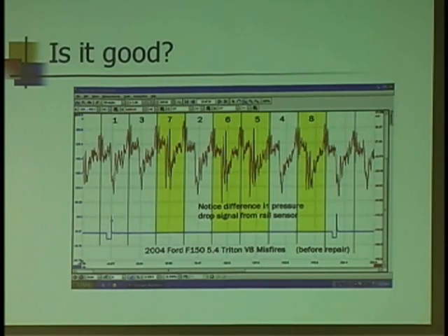What's common to the ones that are nasty? Same bank. They're on the same bank. Now in relation to where the fuel's coming in, where are they? They're on the tail end, right, of this returnless system. So I'm thinking to myself, you know what? I think there's something not right with the flow.